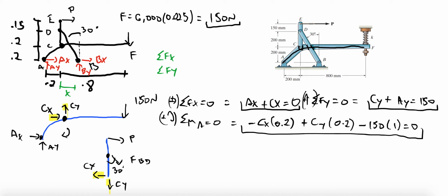That's the key to solving this problem, recognizing that as a two-force member. If you recall, I was struggling in the beginning. If I do that, it means that Bx and By are no longer two separate components. I will already know the direction that the reaction is going. It's going in the BD direction, so there's no need to draw two components. Even though you can still split them into components, you already know the direction. So that said, I can actually erase this whole link here, and I can draw this as a support reaction.